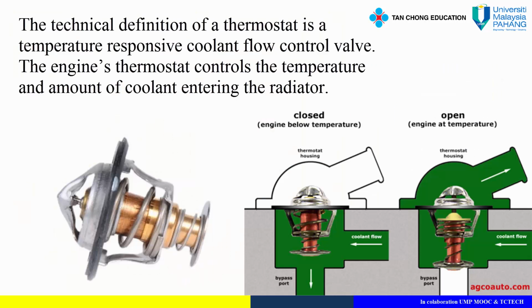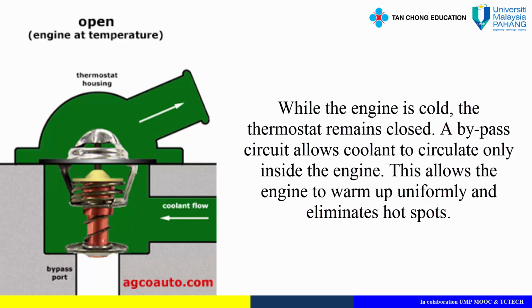The technical definition of a thermostat is a temperature-responsive, coolant flow control valve. The engine's thermostat controls the temperature and amount of coolant entering the radiator. While the engine is cold, the thermostat remains closed. A bypass circuit allows coolant to circulate only inside the engine. This allows the engine to warm up uniformly and eliminates hot spots.